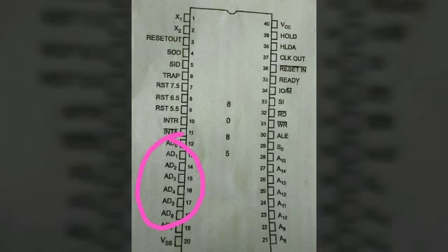During the first part of the machine cycle, that is the T1 time period, the ALE signal is high and the multiplexed lines AD0 to AD7 serve as the lower order address bus, that is A0 to A7. During the remaining parts of the machine cycle, that is T2, T3, T4 and all the others, the ALE signal becomes low and the demultiplexed lines serve as an 8-bit data bus, that is D0 to D7. The demultiplexing operation is done by the latch as well as the ALE signal.